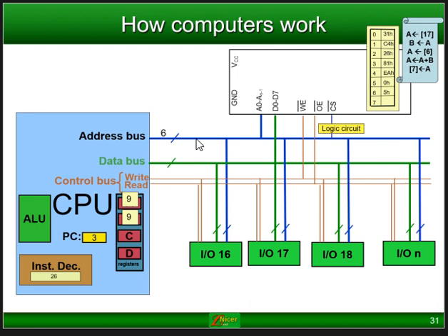This is why the instruction said go to position number 6, address number 6. And this is why the address is now changing to 6, because now it needs to point to that specific position there. And as you can see, that content is moved on the data bus here, and it must be placed in register A. And there it is. It's placed in the register A. So now the next instruction must be fetched again. What is the next instruction?